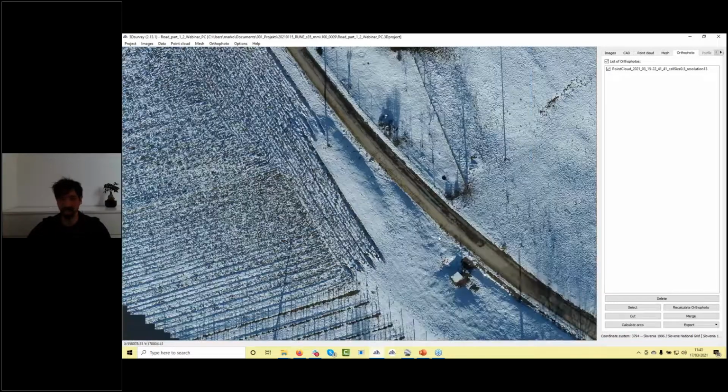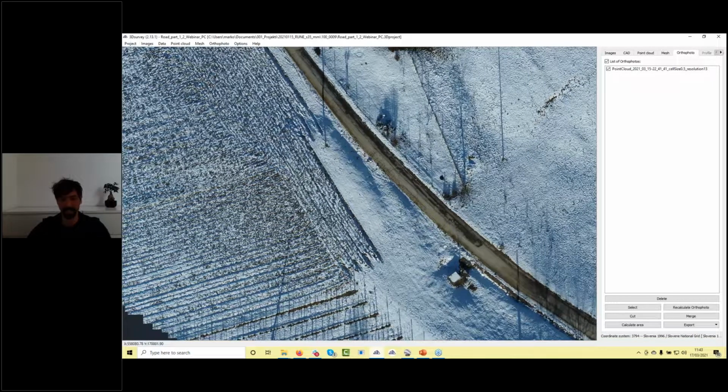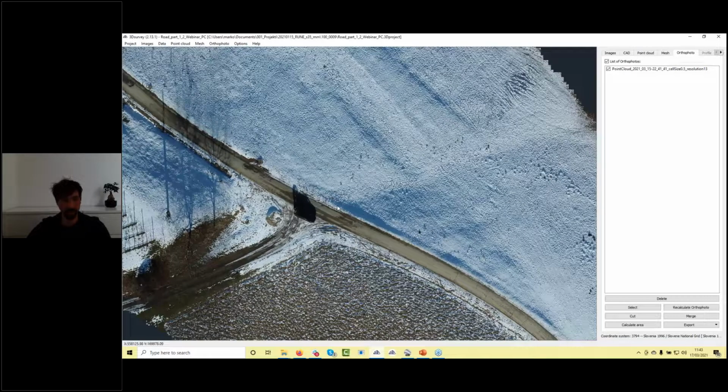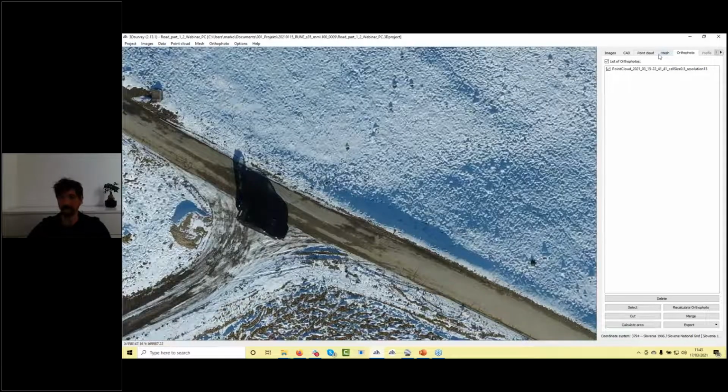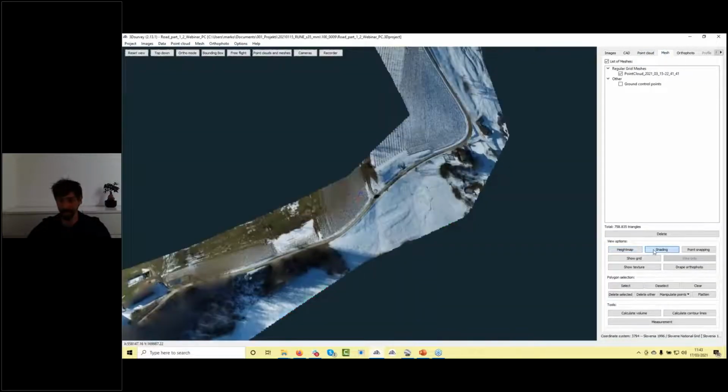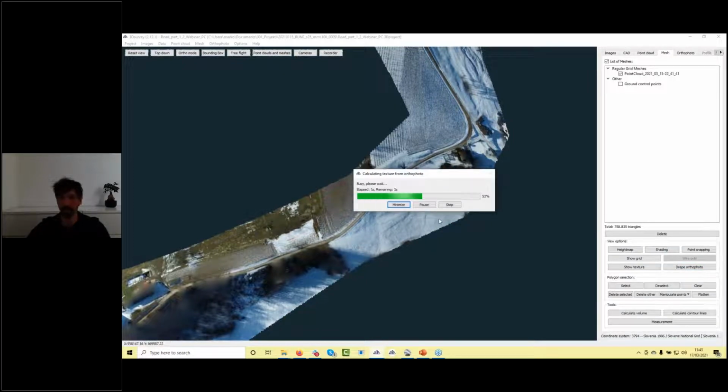So designers need to design where the optical cable should go. And the nicest way to do this is maybe just to drape an orthophoto on my regular grid mesh. So I click on drape orthophoto. Yes, you have the option to select which orthophoto you would like to drape on it.